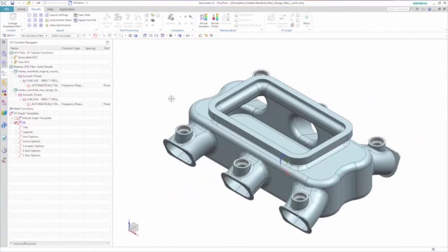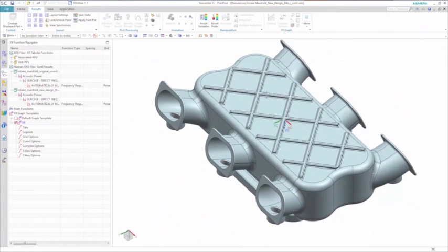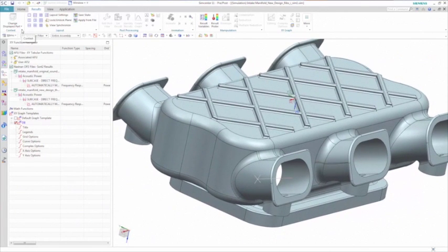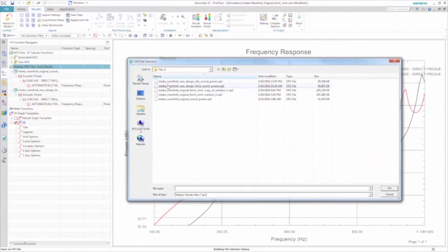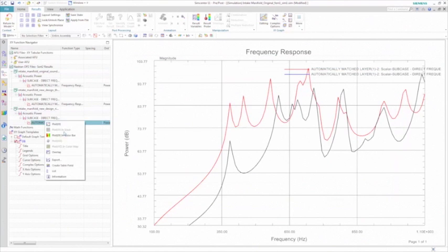Adding thickness is undesirable since it adds extra weight to the part, so you might also look at a third design with ribs. Again, it's possible to update the existing analysis model for the new design and compare the acoustic power results. The noise for this design is not necessarily lower over the entire frequency spectrum. Some acoustic peaks are not changing while some structural peaks are shifting.